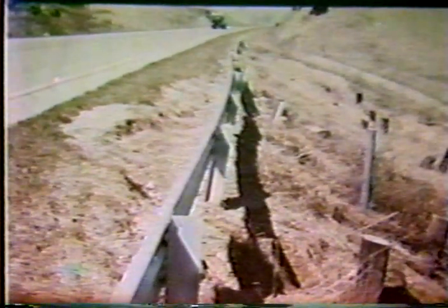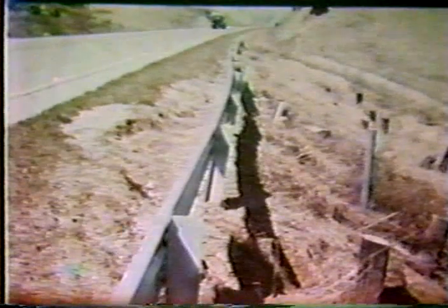He needs that protected. Because that particular type of instrumentation, like Dick had mentioned earlier, may stay in 15 years or more. I have made installations where I've had slope inclinometers at bridge approaches in for some 14 years. And we got a wealth of data from it. Because if you don't hang around to get those kind of slow movements, and these were very, very slow movements, you don't know what's going to happen there.